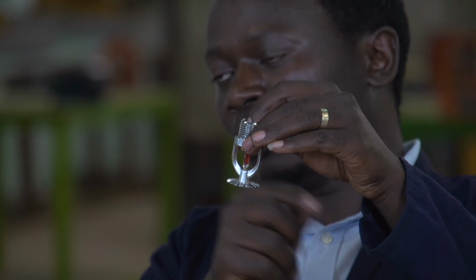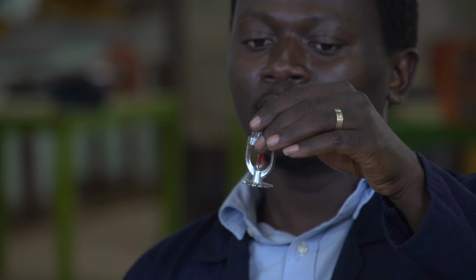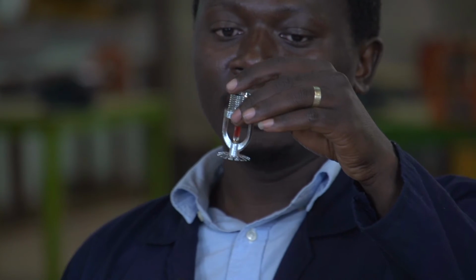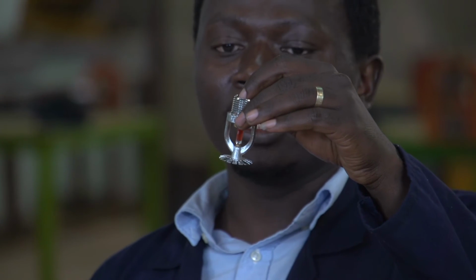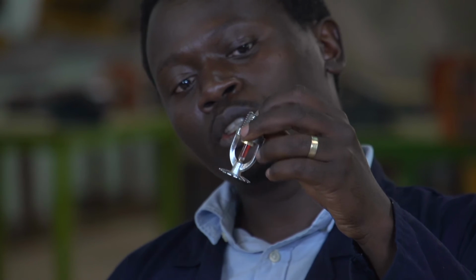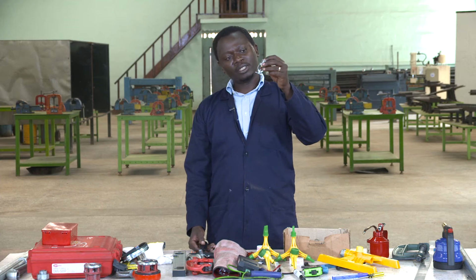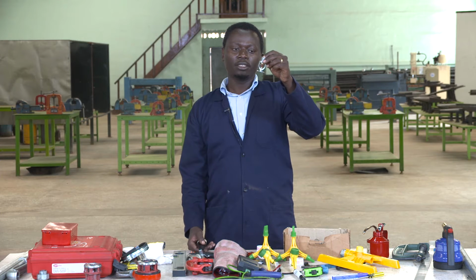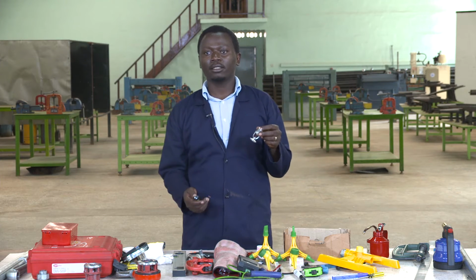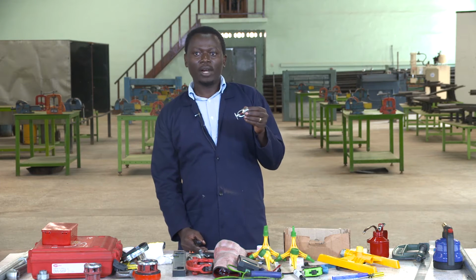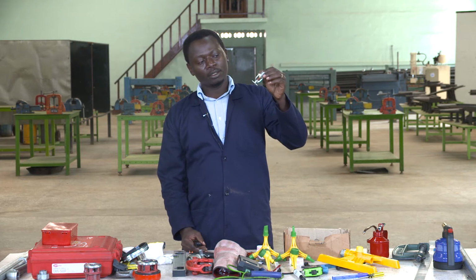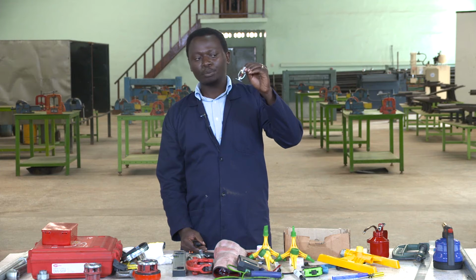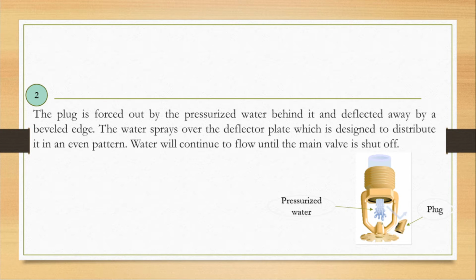the plug and it goes out directly. That will depend on the kind of sprinkler head. If it is yellow, if it is red, you will see according to the color code we have on this kind of sprinklers. So the plug goes out by pressure. The pressure comes from the water main or the pipeline, which has already been installed.